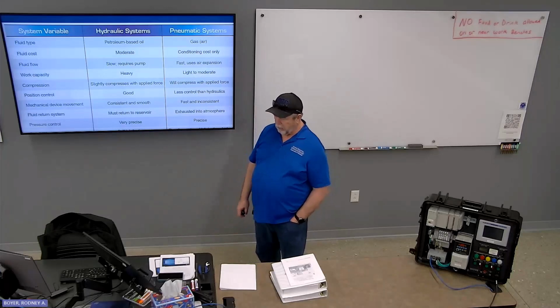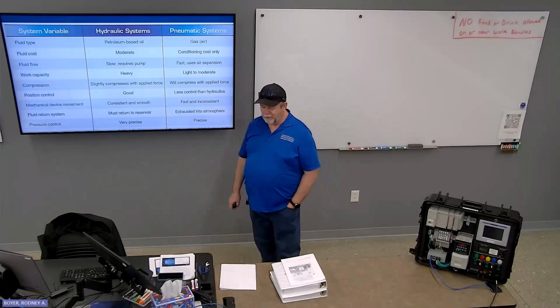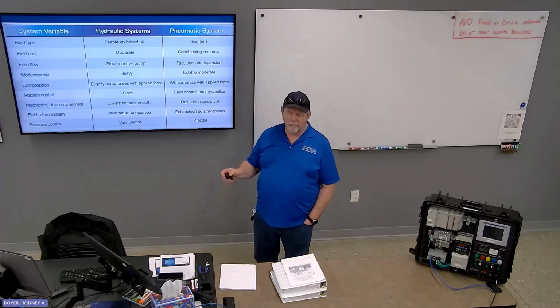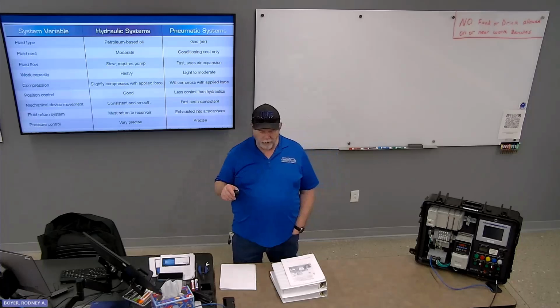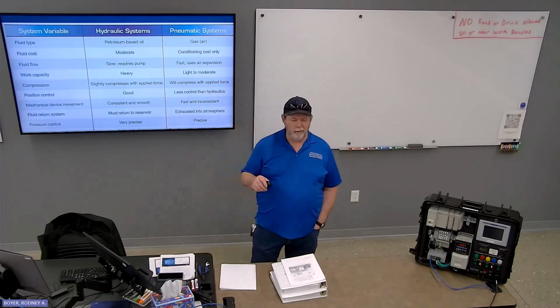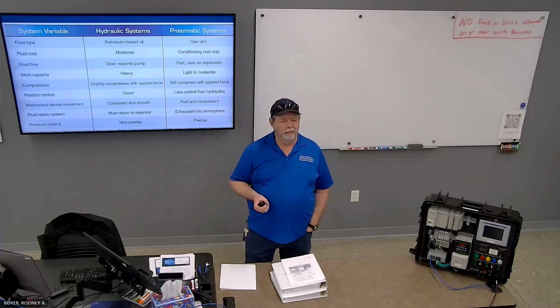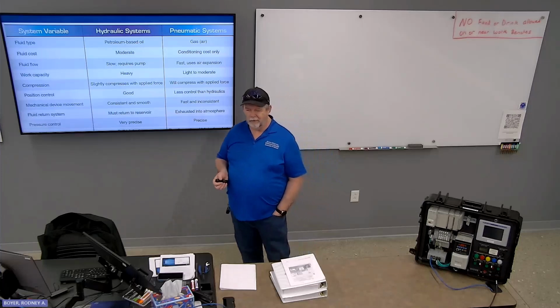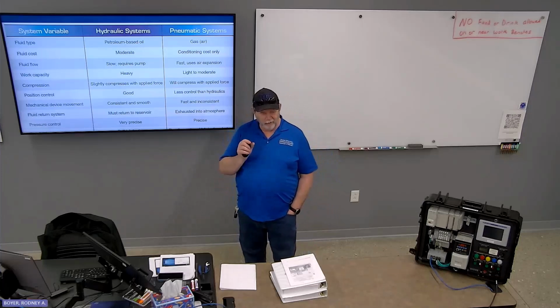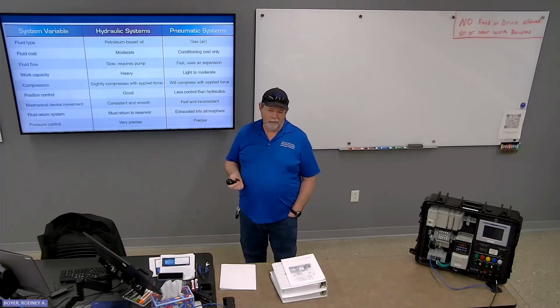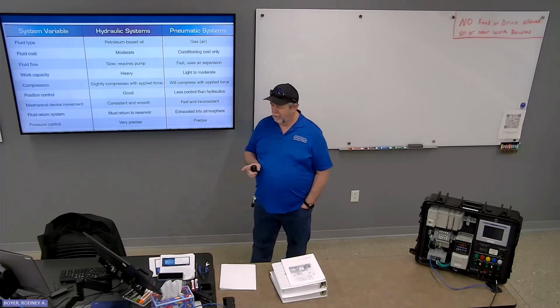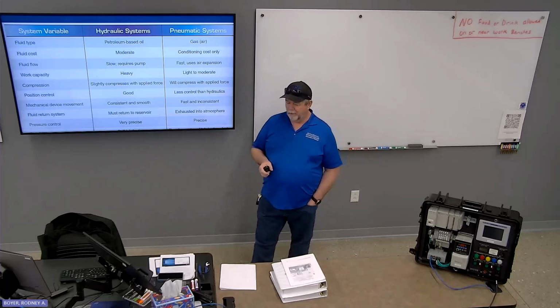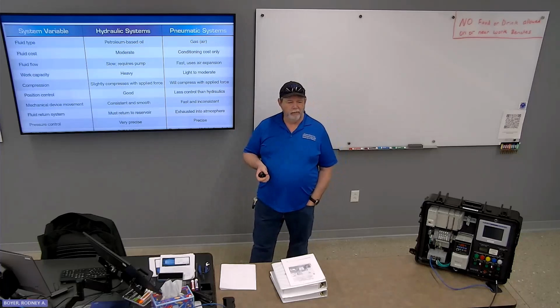Compression: our hydraulic systems slightly compress with applied force. The amount that liquids compress is so small that you can just say that they're incompressible. Okay. Yeah, you put enough pressure on it, squeeze a little bit, but not very much at all. So we're going to say incompressible. And pneumatic systems, you can smash air pretty easily.